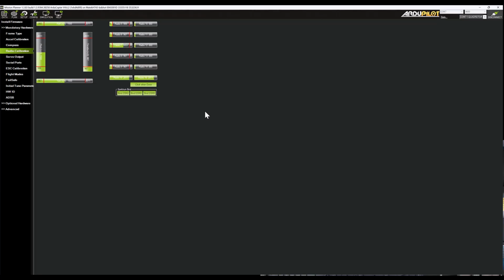Okay, so it just recognized all the values from my buttons and initialized minimum and maximum values, and I can click done to finalize calibration. Let's see if I have one more button. Yeah, nothing else. So let's click done. And everything has been centered, and some changes have been recorded into the flight controller. Perfect. It's done, so potentially we calibrated everything.